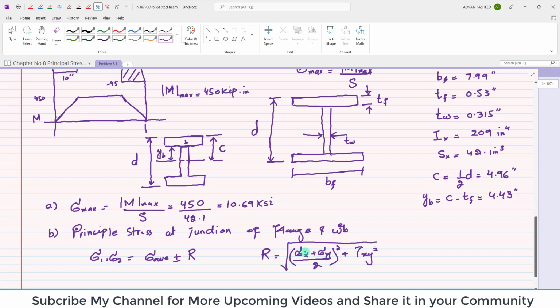Here you will need the normal stress and shear stress at this junction point. So we will first calculate the normal stress at junction point B. This will be equal to YB over C multiplied by the maximum stress.